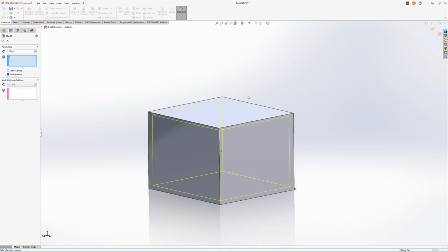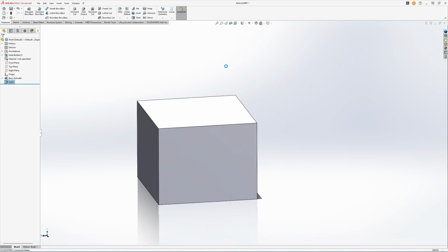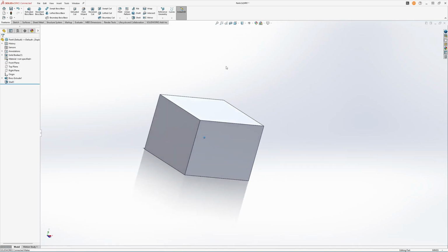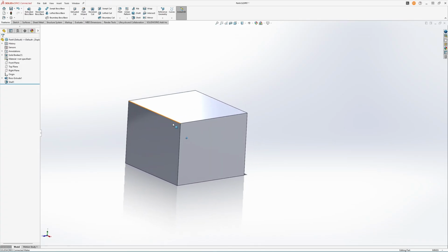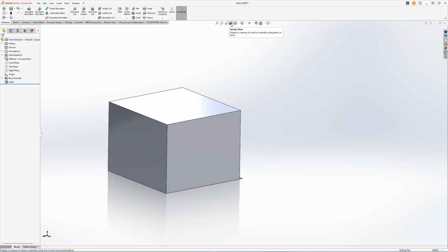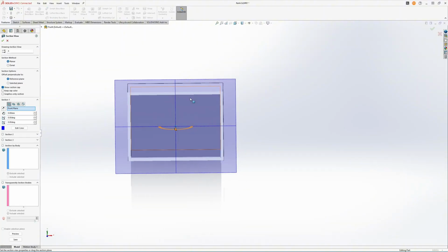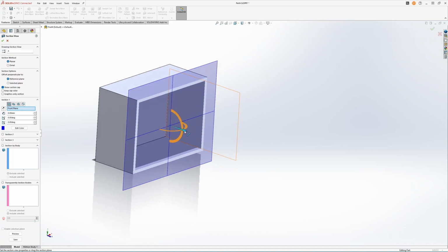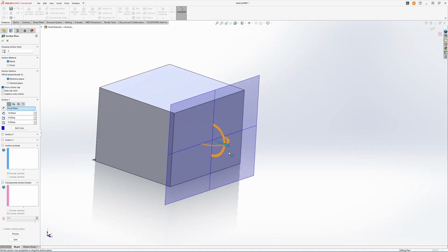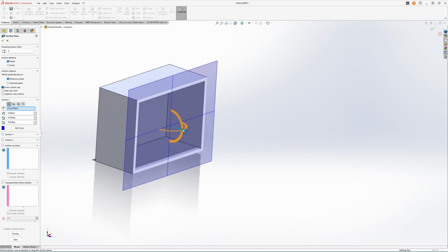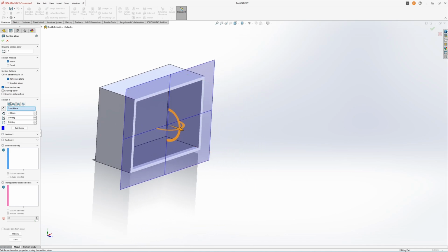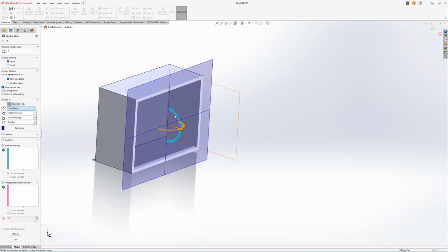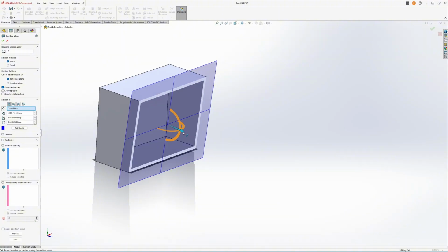So let's try to just create it without removing anything. It looks the same, right? It's just a cube, but it's actually hollow now. And we can see that by using this section view up here. So this section view, as it says in the name, it cuts a section, and you can control where it cuts the section like this. This is section 1. You can rotate that as well and drag it.